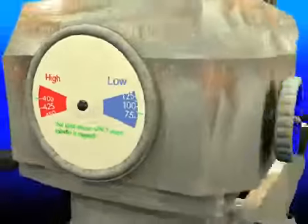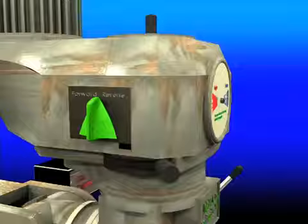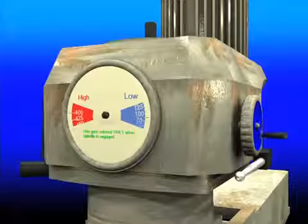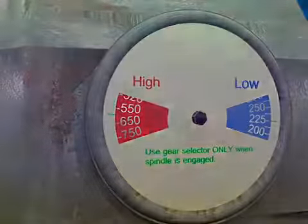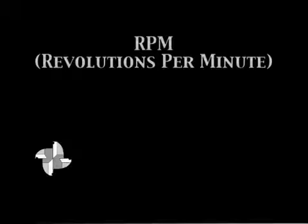Now that we have our speed, the proper method to set the machine to this RPM is to switch to high gear while the spindle is off, and then turn the spindle on. Make sure that the cutter is rotating in the proper direction to make a cut. And then adjust the speed dial to the suggested RPM. We have covered how the RPM represents the tool's rotations measured in minutes.